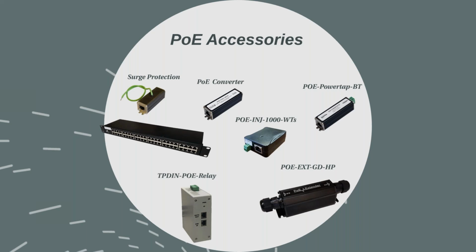Well, you can plug this in. It is 802.3 AT compliant. This is outdoor rated IP66, so you don't have to have an external enclosure or anything like that. Plug in your Cat5 cable, run another 100 meters, and you can daisy chain several of